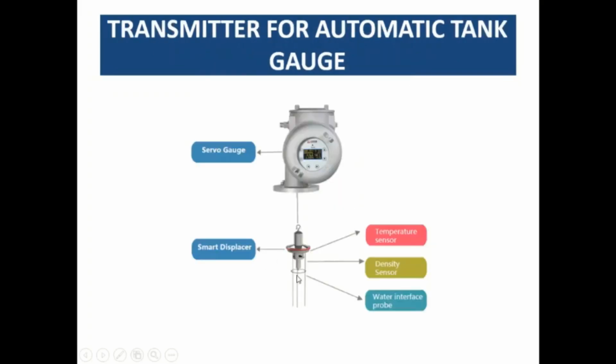Once this pointer moves downward or upward, in response you have attached a digital device which is calibrated accordingly, and that may convert this signal into an electrical signal and transmit it to your control room, and in the control room you can easily assess what the level is in a particular tank where you are pouring your final product, or from which you are taking the raw material.